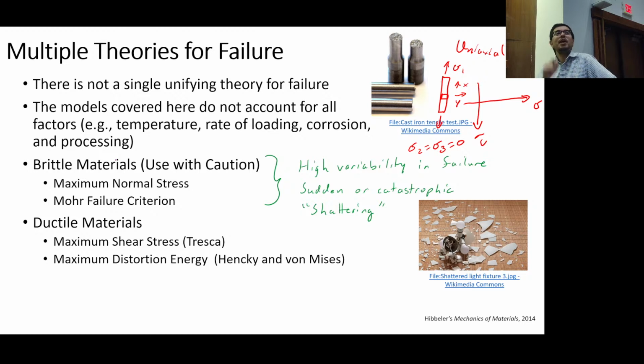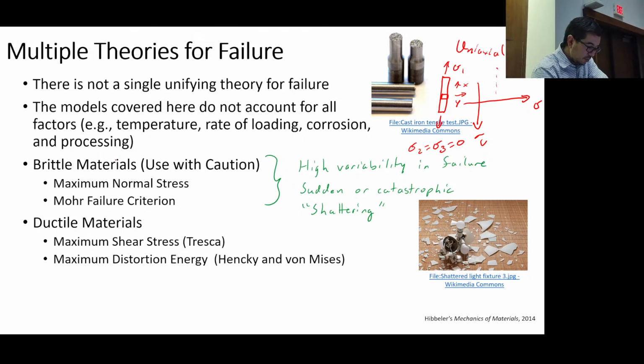So then tell me, how do I draw a Mohr circle? So you want to get the average. Yes. So basically, the center is sigma x plus sigma y over 2. And for the radius, it's basically the square root of sigma x minus the average, squared. Okay, so you're telling me I have a sigma average, right? And what is that equal to? Basically, sigma x plus sigma y over 2. Yes, and then simplify. Half of sigma x, or half of sigma 1, the way I've described it. So it's just sigma 1 over 2, right?